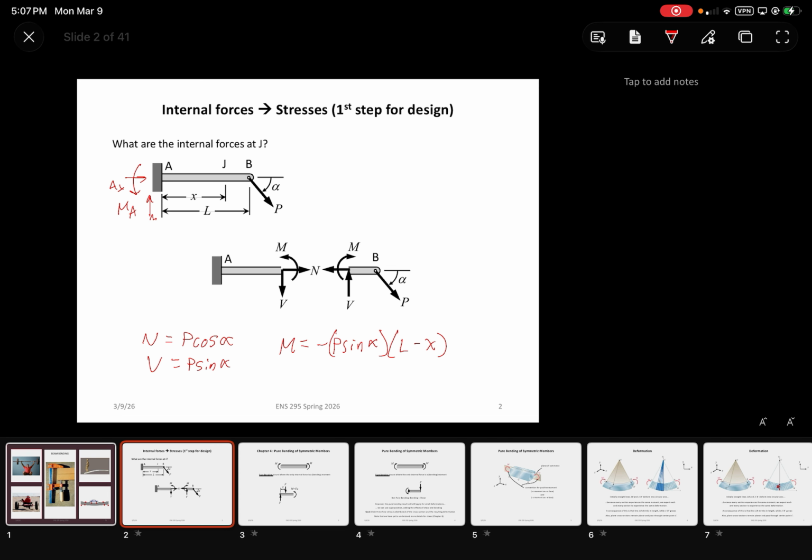We'll do plenty more examples. I know it's a little bit confusing, but basically these internal force equations come directly from analyzing force equilibrium where you're cutting the beam, right? So you basically treat the cut as if it's a fixed end. Does that make sense? Awesome.